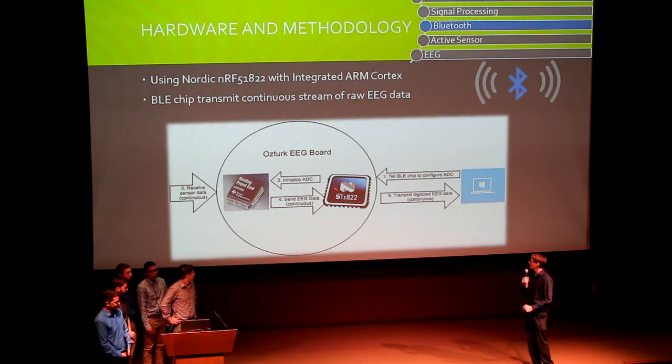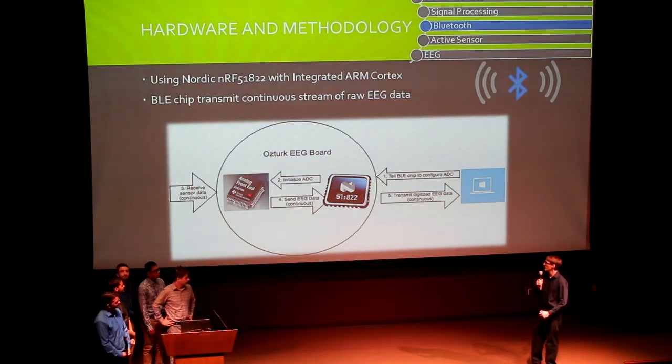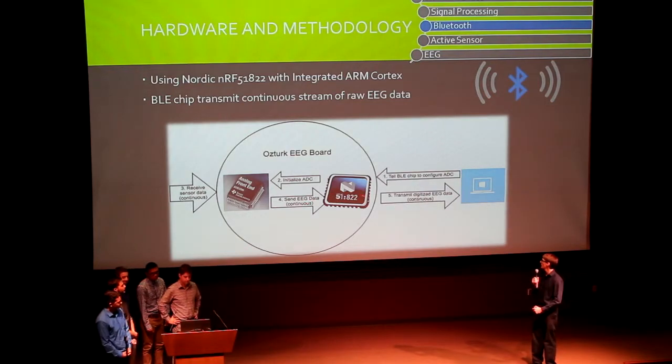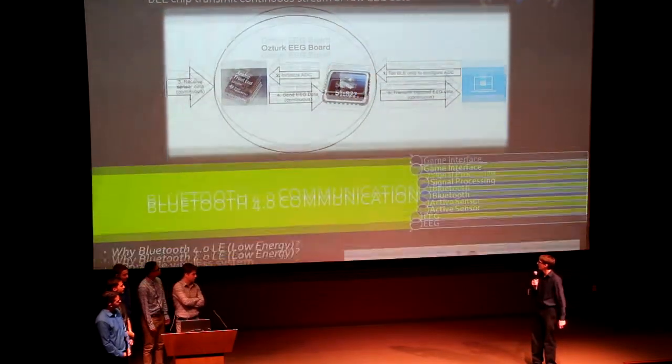Then the Nordic chip with the Cortex M0 sends those to the ADC, which starts reading in the sensor data continuously, and then digitizing that, sending it back to the Bluetooth chip, from which it will be sent back to the host application for signal processing.